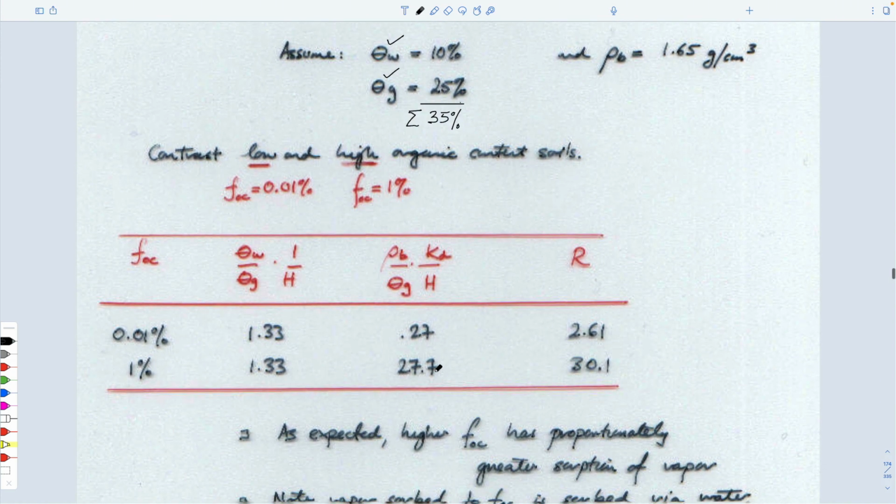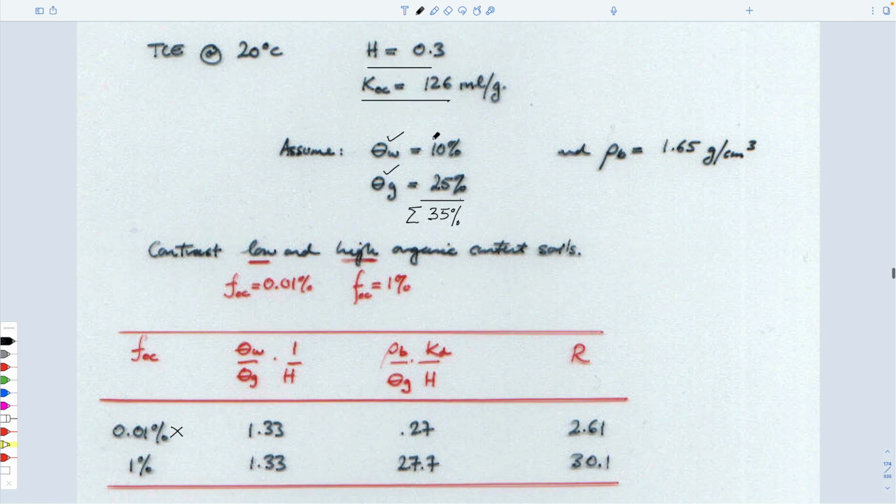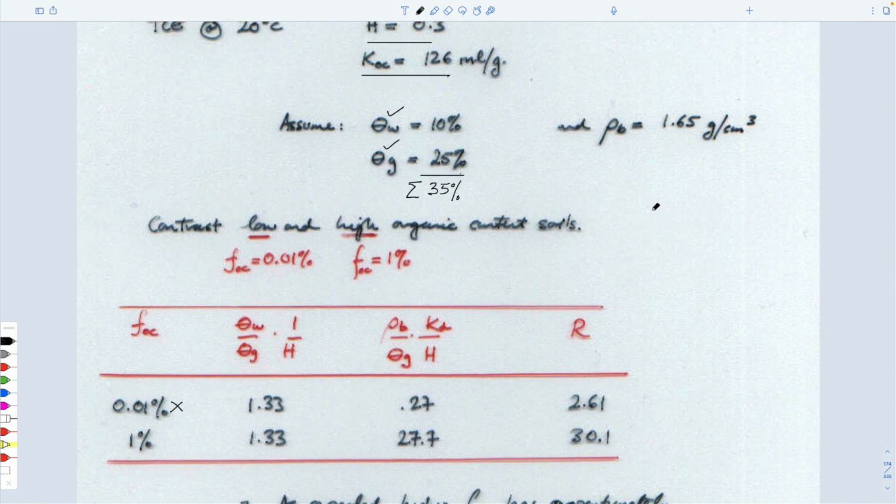And then we can just look at what these individual components would be. And so if we look at scaling it with organic carbon, well, for this one, we probably shouldn't be using this relationship, right, from what we've talked about. We shouldn't be using Kd is equal to KOC times the fraction of organic carbon. We should only use this if the fraction of organic carbon is greater than, didn't we say 0.1% within the aquifer? So we probably shouldn't be using it for this.